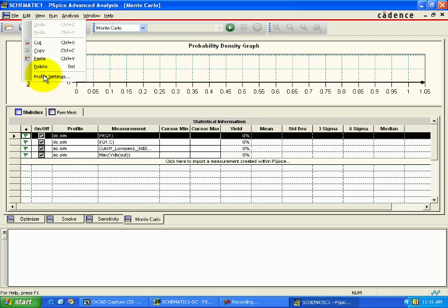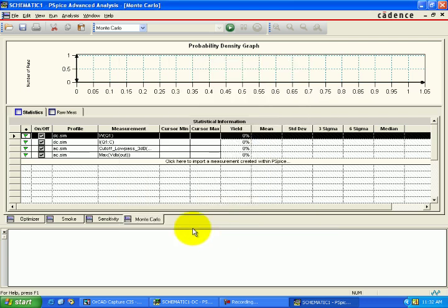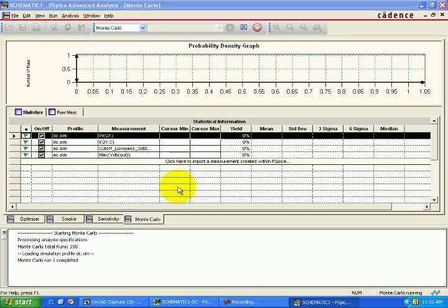So we have selected all the DC and AC simulation, all the parameters for statistical information. And in the profile setting, we will set the number of runs. We select 100, so the Monte Carlo analysis will run 100 times. And all these parameters are the Q1 power dissipation, current from the collector of Q1, cutoff low pass 3 dB, gain at the voltage. So that's how it started.